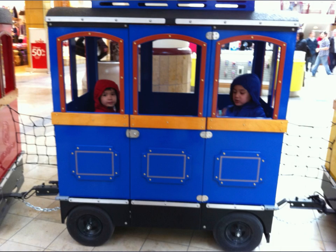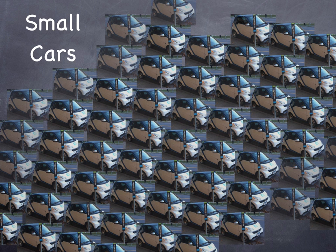Think about a train. How close together are cars on a train? Well, they touch. If traffic were perfectly predictable and autos didn't brake, they wouldn't need any space on the road between them. In technical terms, they would have a headway of zero as many cars as wanted to could pass a point at free flow speed, say 60 miles an hour, subject to their having physical length. They could operate like a train. And if cars were infinitesimally small, we wouldn't even have to worry about length, and then there could be an infinite number of cars going through the bottleneck.